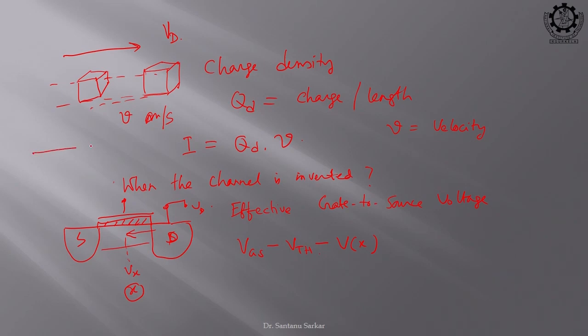You all know that, because suppose there was no drain potential, my channel would be uniform. Now, suppose I start to increase my Vd, so this will fight with this field, and this channel will become tapered. You know this. If we further increase our Vd, what will happen? This channel will end before it reaches the drain junction. Why? Because the effective voltage is now what?